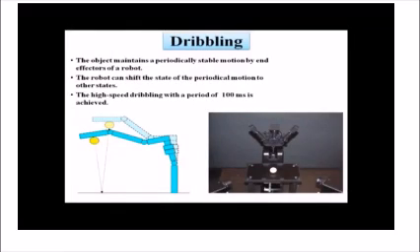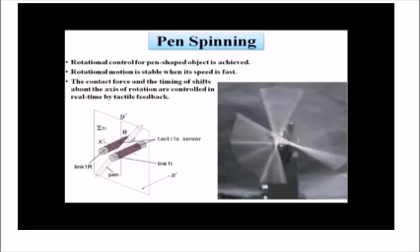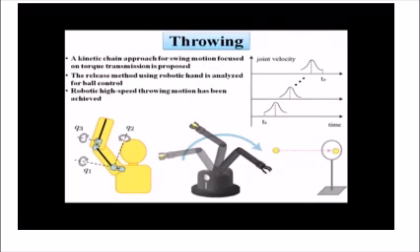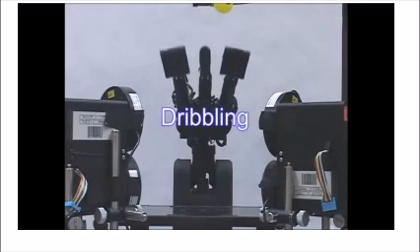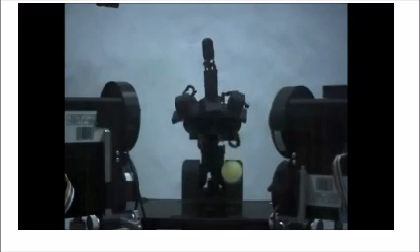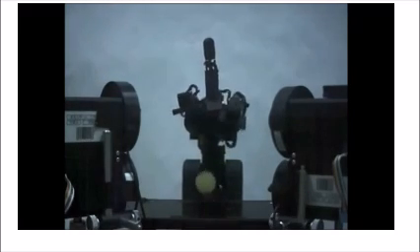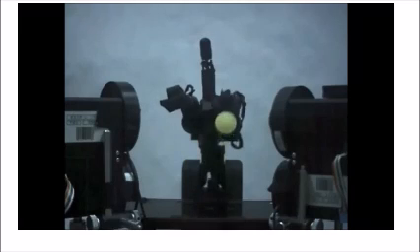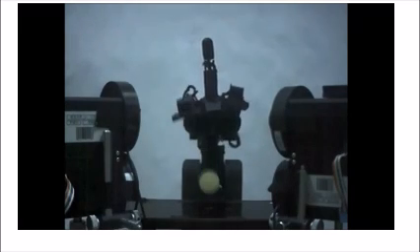High-speed control improves not just the speed of existing robot manipulations. Pursuing the upper limit in terms of speed for mechanical systems, we developed appropriate new control methods for high-speed manipulation. This is dribbling. High-speed active control enables the maintaining of a periodically stable motion. We call it dynamic holding. The dribbling period is around 100 milliseconds.